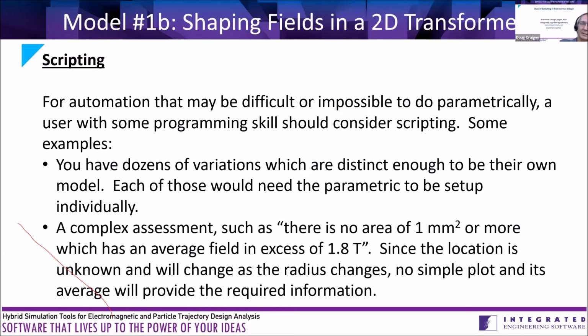The other thing I mentioned here is, if you have a complex assessment, there may be no simple built-in tool for something like: tell me if there's any area of 1 millimeter squared or greater which has an average field in excess of 1.8 Teslas. It's a very specific, complex assessment that you figured out is important to you. People often do this for electric sparking types of troubleshooting, and they're looking at this kind of issue for high fields for saturation purposes.